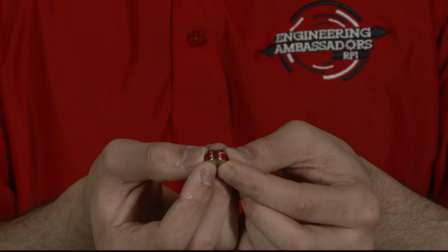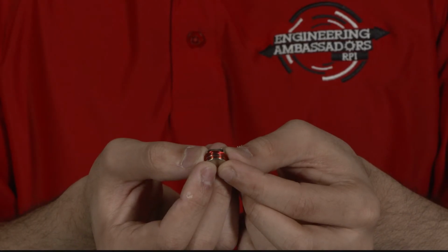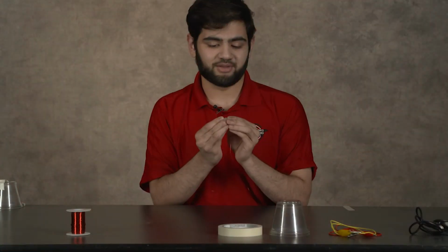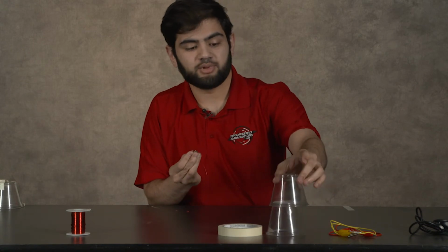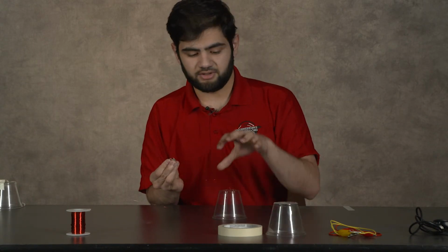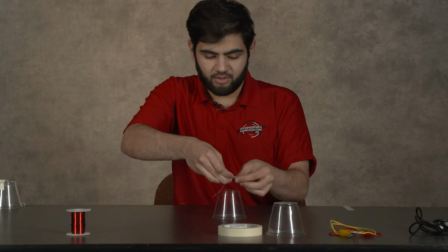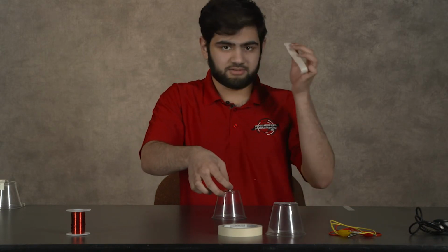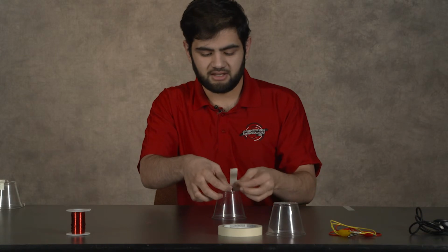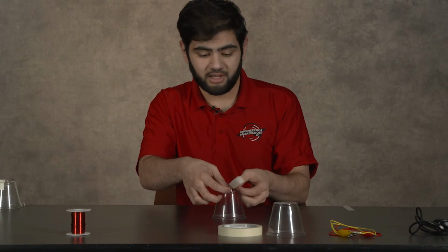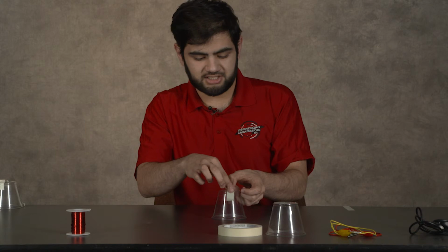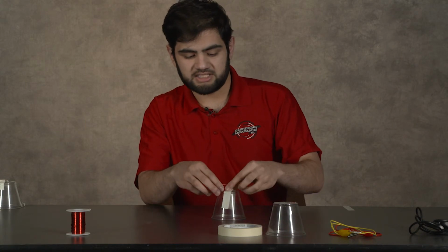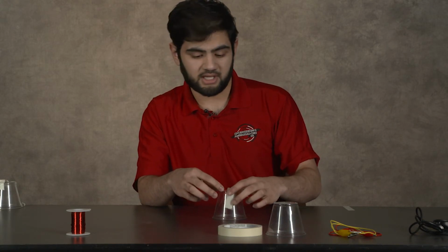Okay, so now that you've formed a good enough coil, again, the problem is this wire really likes to slip on the magnet. So immediately take your plastic cup and set it face down so the opening is pointing down, and just lay your magnet right in the center on the top of that plastic cup. Then take some amount of tape that you've set aside, or just ask one of your partners that you're working with to help you out on this, and just stick it down. Use the sides of the cup and just tape that magnet down to the surface as best you can.